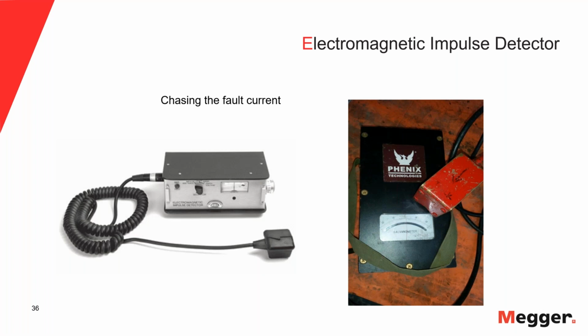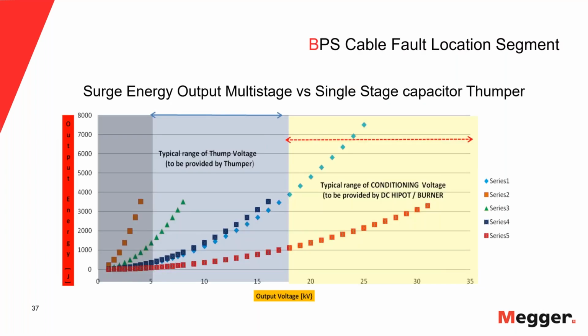Okay, because a small signal is better than the wrong signal. All right, one other quick aspect of thumping and energy and noise. Many of the old thumpers were network thumpers, single-stage thumpers. Many of them had a rating of 25 kV surging, and there might be 7,500 joules.